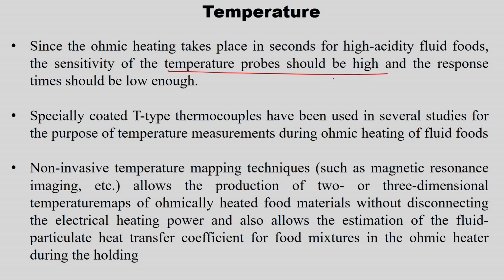So, this is also another important criterion when we use thermocouples to measure the temperature inside the food material, because the probe's sensitivity should be high. Sensitivity in the sense of how fast it measures the temperature and gives the digital display. And also the response: if I keep the thermocouple, how fast does it respond to the temperature difference, and how fast will I be able to get that data recorded.